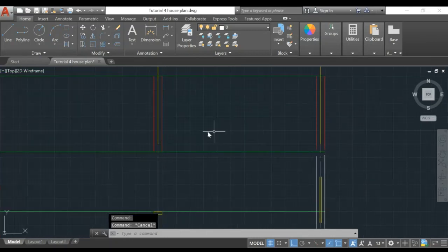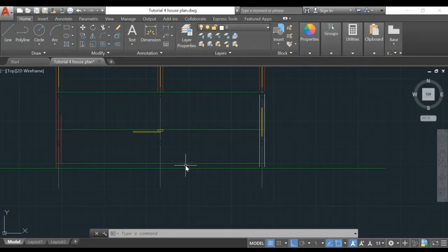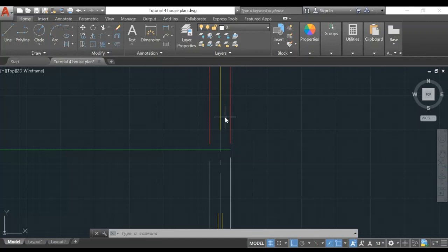That's why colors to indicate layer line thickness is important. It means that the color you create is 0.4, right? Okay, the yellow color here is 0.3, and the pink color is 0.6. If you're using all black or all white, you do not know the thickness of the line. And in technical drawing, line thickness is very important. You mess up with line thickness, your technical drawing will be wrong. Your drawing will be misunderstood by all professionals, even contractors. All right. So it's very important. So this indicates as 0.4 or 0.5.